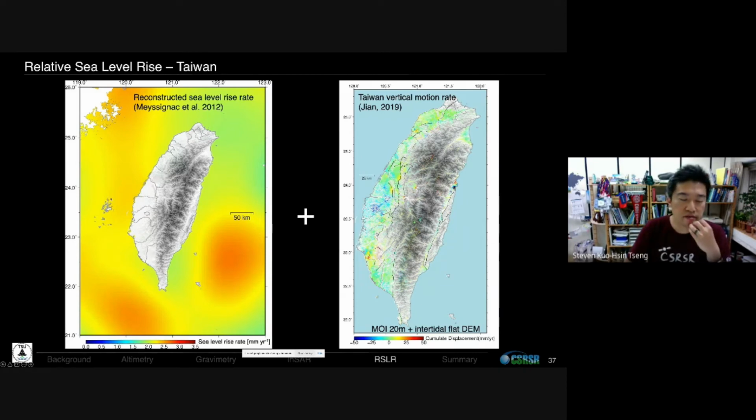You can get the sea level rise rate, and you can check what the worst scenario or the moderate scenario is near the coastline of your country, and put the number along the coastline and try to simulate the relative sea level rise and where the area is that has a higher flood risk. Of course, you need a good DEM though. The part I didn't mention is that we also construct a very good intertidal zone DEM.